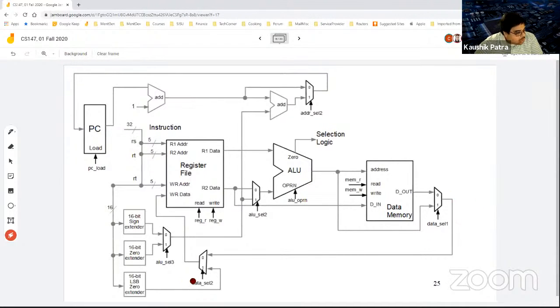And there are a lot of other multiplexers to be considered, along with the register file control and the data memory now coming into the picture. We have the PC load anyway. Those kinds of things you need to consider instruction by instruction. And similarly, if we combine them together in a complete data path, which supports all types of instruction, R, I, J, then we have many control signals to set to the correct value at the correct execution phase.